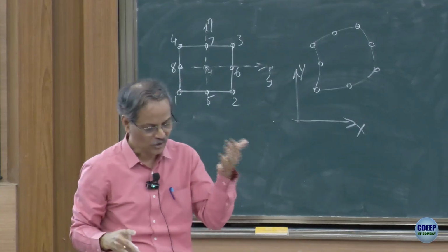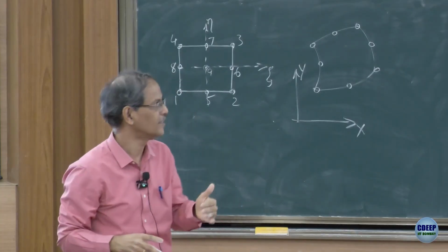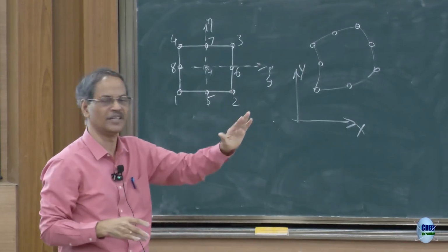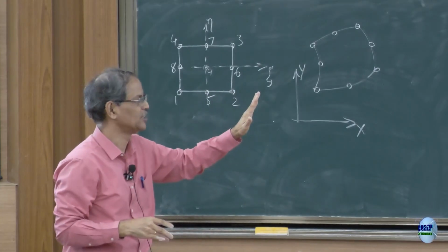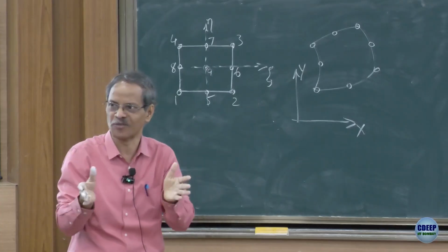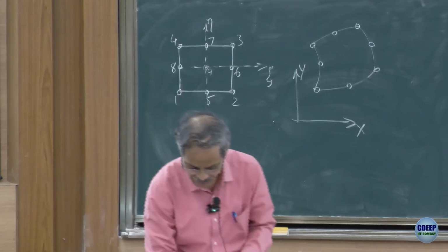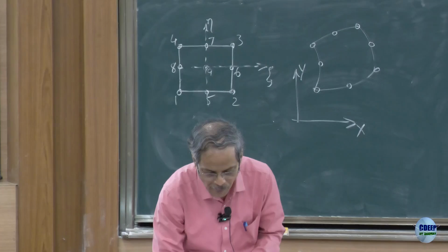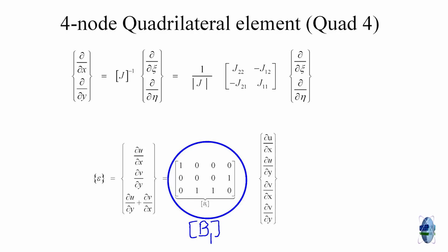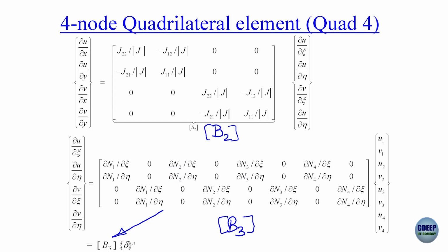Okay. Once you have done that, then you differentiate it, you would get same b1, b2, b3. b1 does not change, 3 comma 4 remains a set of zeros and ones, it is not changing whatever we got earlier. b2 is, let me see, it is here or it was here. Yeah, b1 was this zeros and ones, that does not change from one element to another element. b2 is the set of Jacobians repeated twice. So, it is a 4 by 4 matrix.